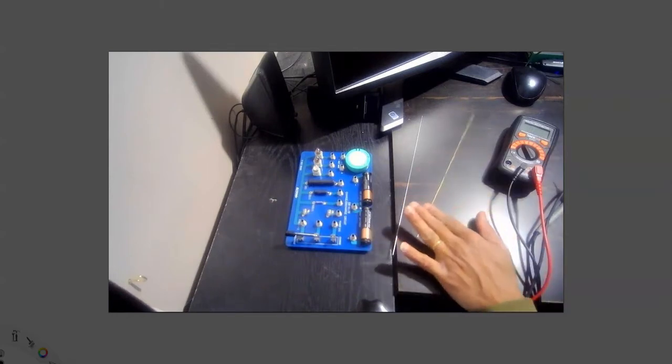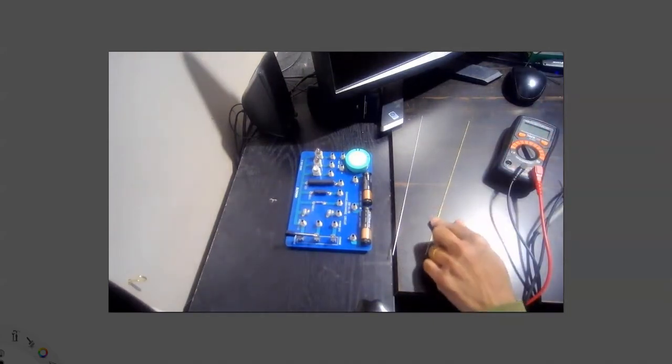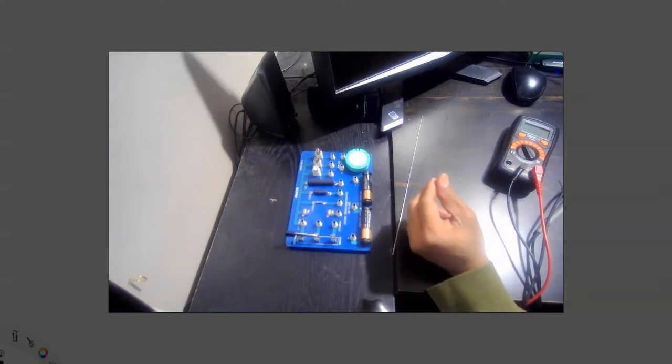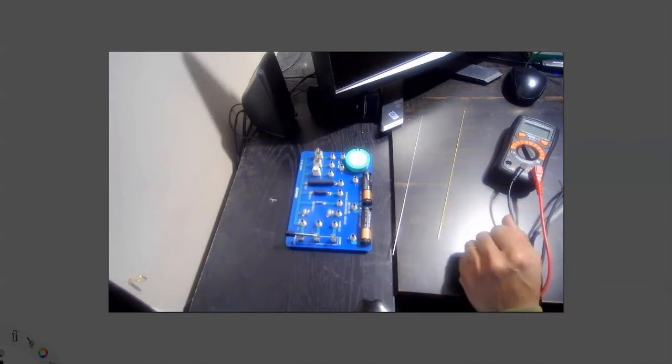The other method is, we're not going to directly measure the resistance. That's this lab. We're going to figure it out in a different way. The other method is finding the current and voltage across this conducting wire. This acts like a little resistor, right? Even though it's a good conductor, there is some resistance in it. So when we have current going through it, there will be some voltage, there will be some current. By measuring those, we can calculate what the resistance is.